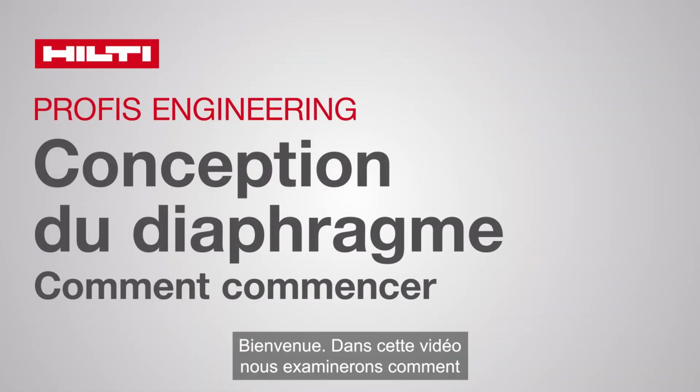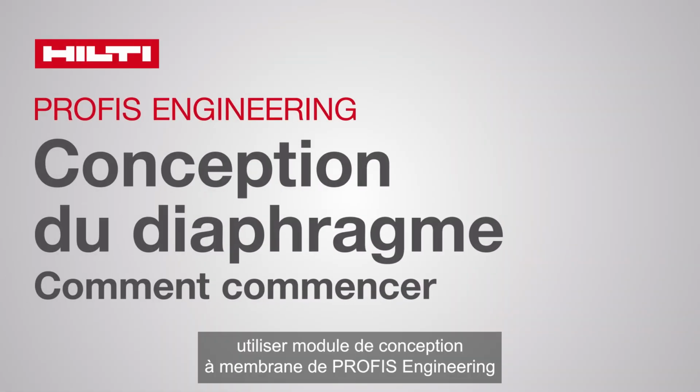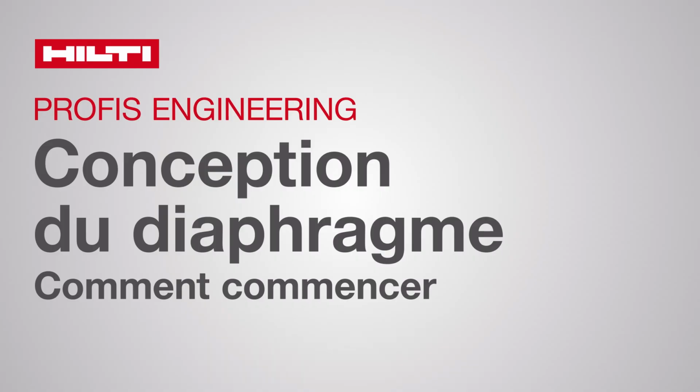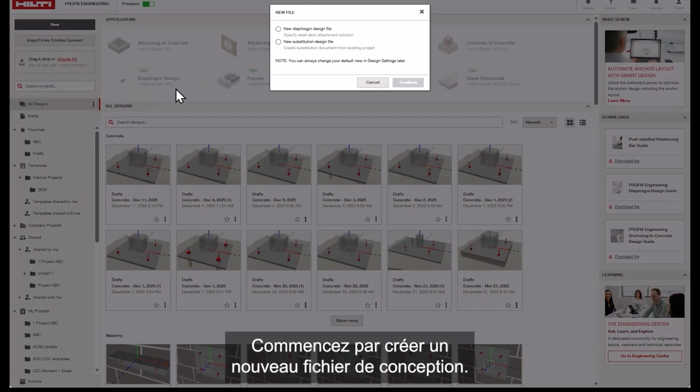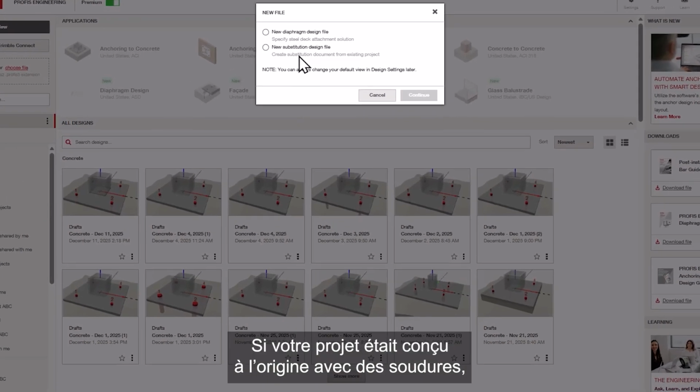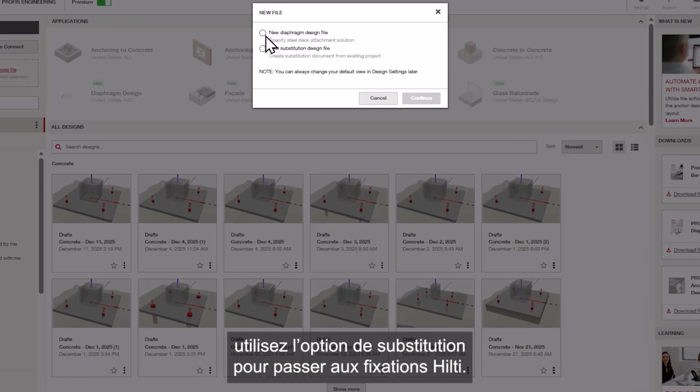Welcome. In this video, we will walk through how to use PROFIS Engineering's diaphragm design module to design metal deck attachments. Begin by creating a new design file. If your project was originally designed with welds, you can use the substitution option to switch to Hilti fasteners.